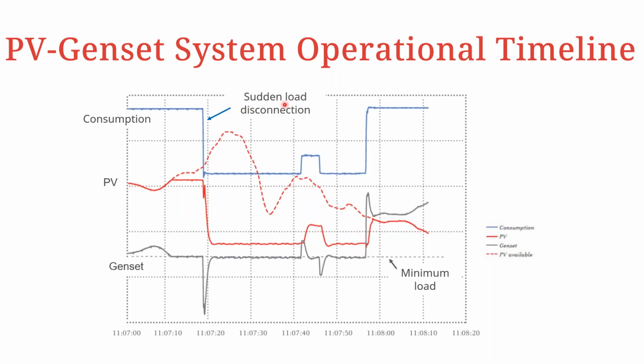If we have a sudden loss or disconnection of a load, the system will need to power down, but if we didn't have a controller in the system, we would still be producing that power. With the controller, it allows us to automatically switch down the system, which allows for extremely fast reaction from the PV, so it ramps down in conjunction with the load being lost.